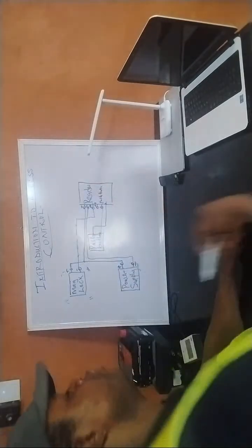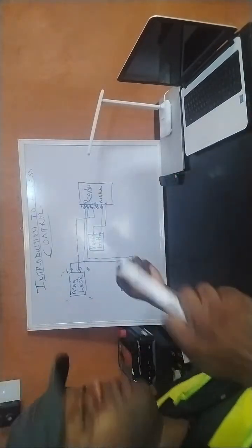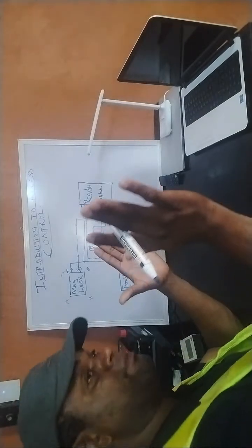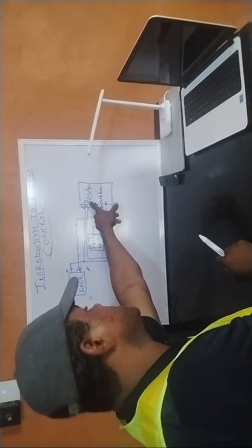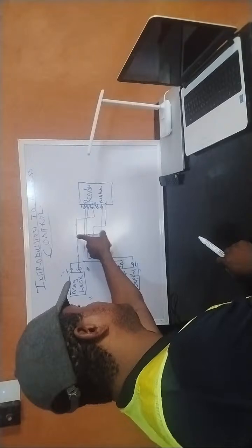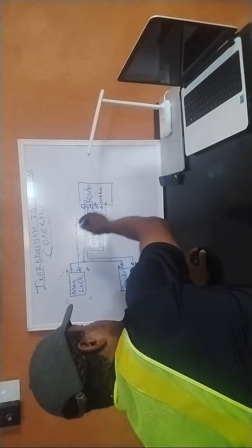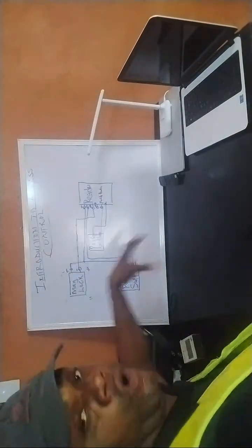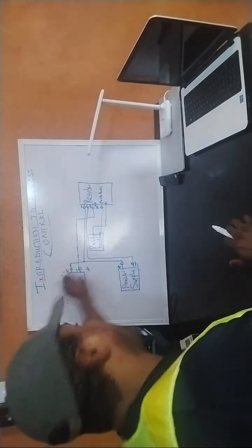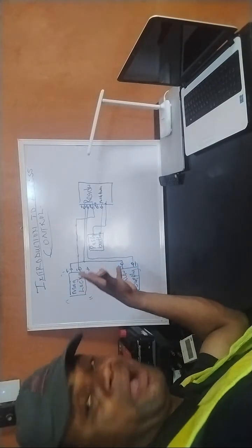This is where your door closer comes into play. So maybe you open that door and you walk in, while the door remains open, your door closer closes and begins to bring it back. Once the timer times out, if it's a 5 seconds timing, automatically this part of the circuit, for example this line that was broken, closes again after 5 seconds and sends power to this magnetic lock. There's induction in that coil, a magnetic field is generated, and it magnetizes your door. So this is how it operates for your magnetic lock.